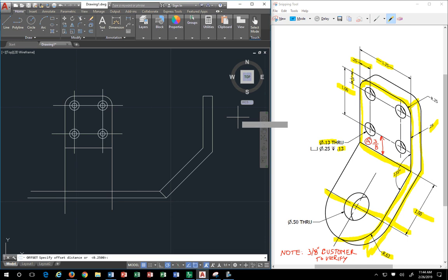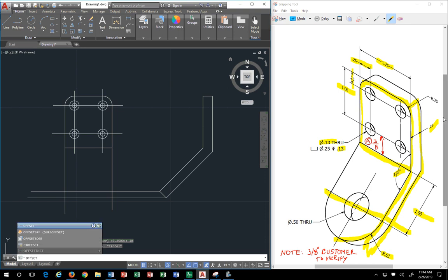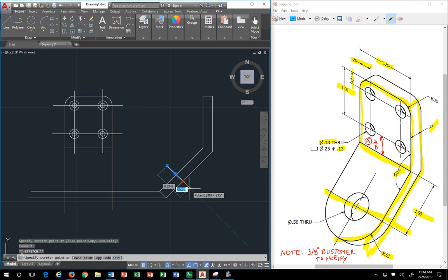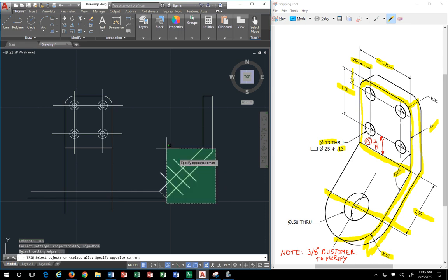Okay, when we're showing a true projection across as we are, we do need to have a few things in. The offset, we need to have the center line identified for where the hole belongs in this view, okay, which is this mark right here. That will become the center line. See? We will need to know the edges of where that hole will be, since the hole is 1/2 inch diameter. Then we're going to offset a 1/4 inch both ways. We are going to trim again, of course, so I could trim off the pieces that don't belong there. So we have that reference, right?